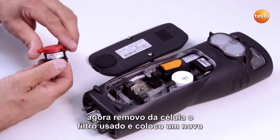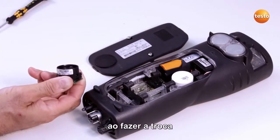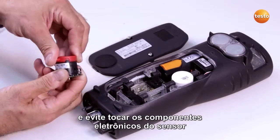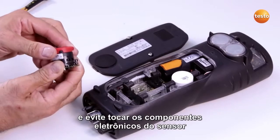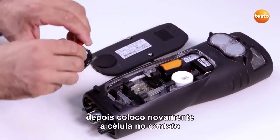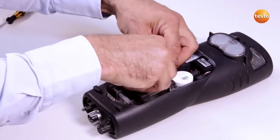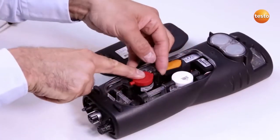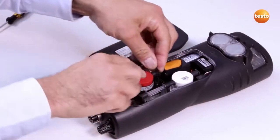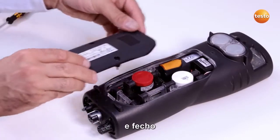Now I remove the spent filter from the sensor and put a new one in. When replacing the filter, I need to make sure that all markings match up and I avoid touching the sensor electronics. Then I insert the sensor back into the slot and connect the sensor to the hose connections. Finally, I put the cover of the sensor compartment back on and close it.